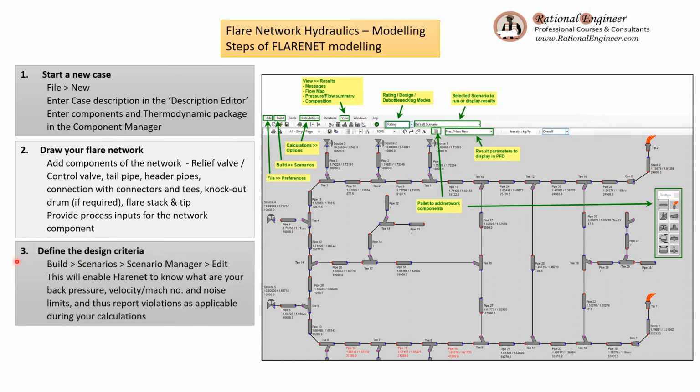Next, you can define the design criteria using built-in scenarios, and in the scenario manager you can edit this. Here you can specify the back pressure, Mach number, noise limits, so that any violations will be highlighted by the software.